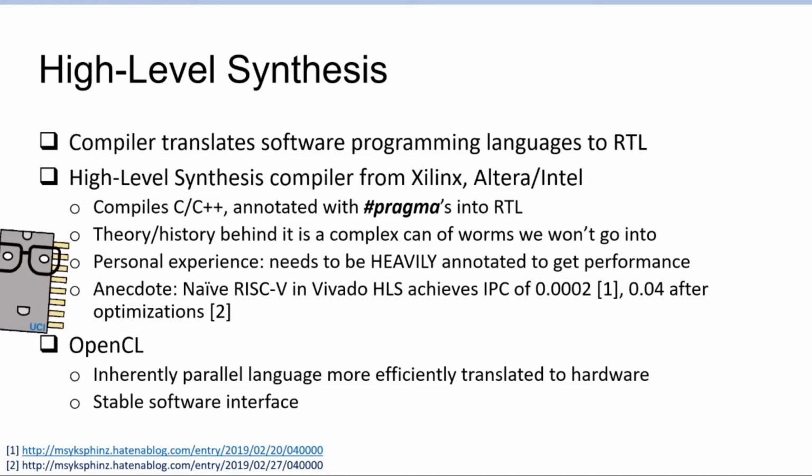But unfortunately, from my personal experience, for HLS to actually work efficiently, everything needs to be heavily annotated to get the performance that you want. And you actually have to start from a pretty good understanding of the RTL level stuff to begin with, to know what to pragma efficiently.